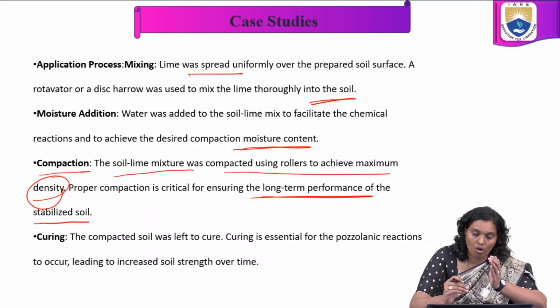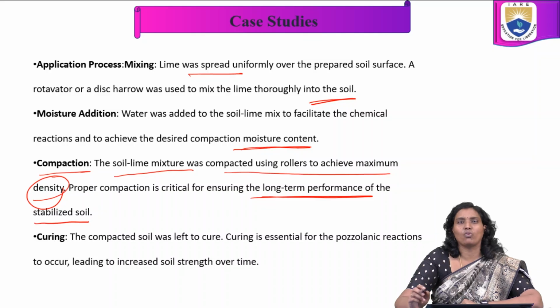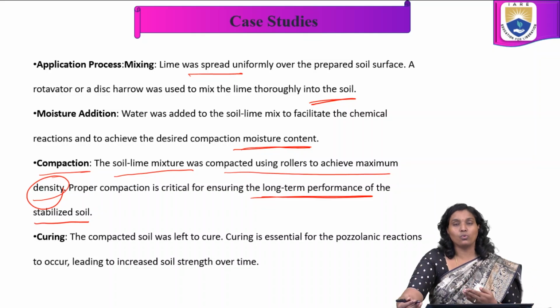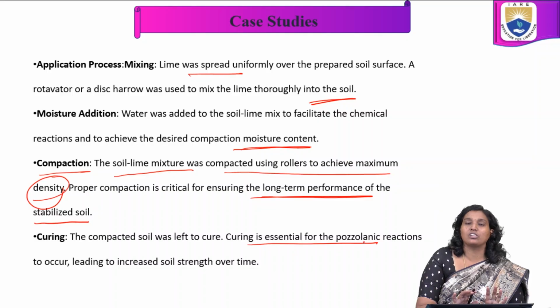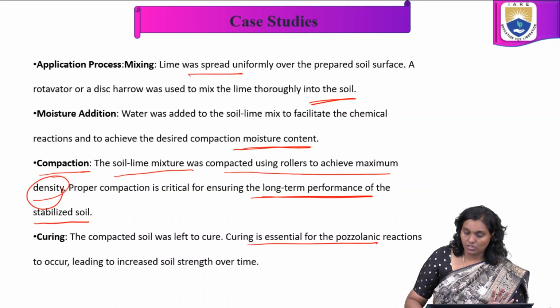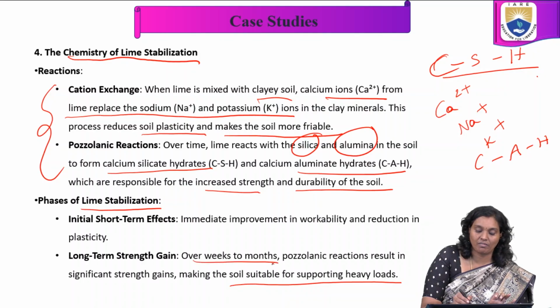Now curing. The compacted soil is left to cure. Curing is essential for the pozzolanic reactions to occur, leading to increased soil strength over time. The pozzolanic reactions, as we already discussed, take place over weeks to months.